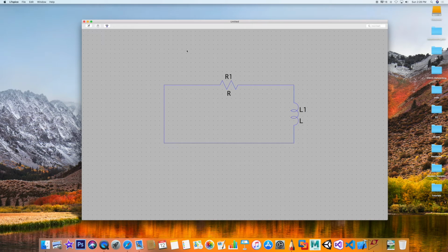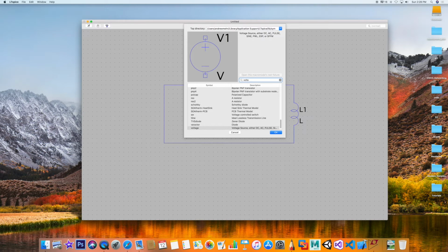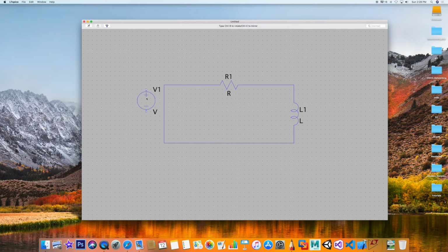I need a voltage source here, right? So a power supply. So I'm going to right mouse click again, draft, component, just type voltage. And notice I didn't even finish. It's going to ask me, do you want a voltage source that is either DC, AC? I'm just going to say okay, and I'll set it myself to what I want. So put it in here, right here, then hit escape, and I'm not drawing any other one.